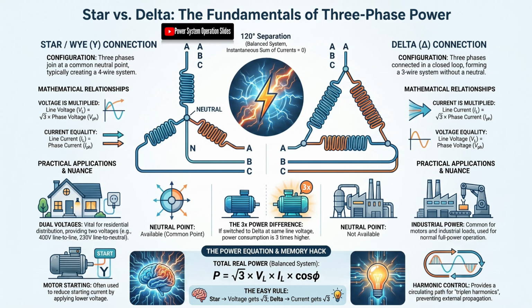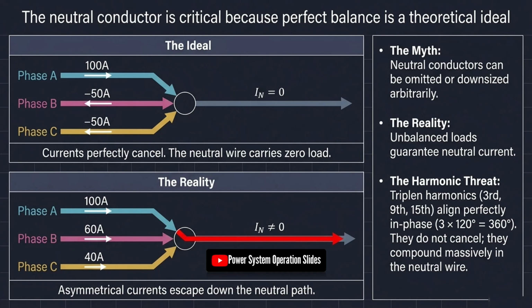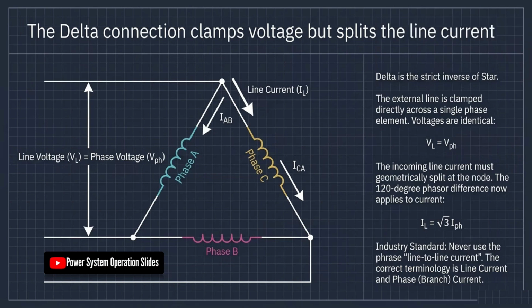The star connection also provides important grounding and protection benefits. The neutral or star point can be connected to Earth through a solid connection or through an impedance. Grounding the neutral establishes a stable voltage reference for the electrical system and provides a predictable path for fault current when a phase conductor comes into contact with grounded equipment or earth.